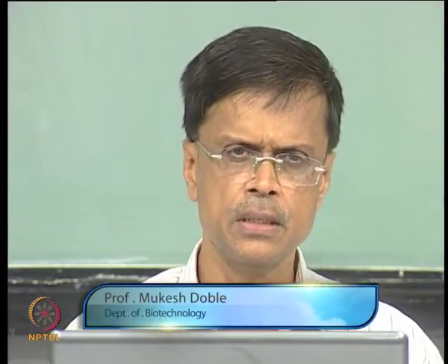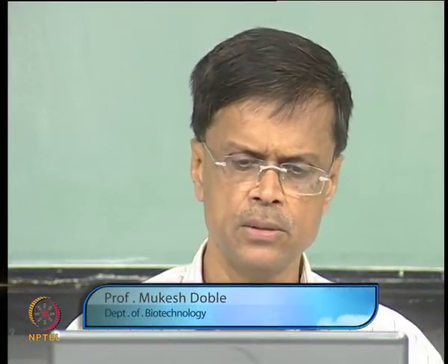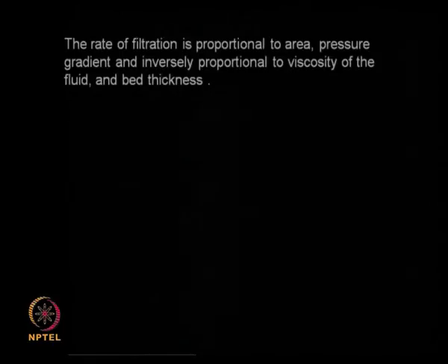We have been talking about solid liquid separation, and we will continue with the same topic today as well. The most important equation is Darcy's law, and Darcy's law relates the throughput that needs to be filtered, or the velocity of the liquid flow, as a function of the pressure drop, the surface area for the filtration as well as the bed thickness.